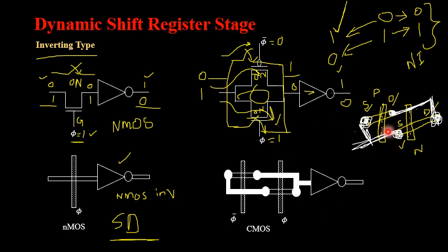Since I have told this particular transistor is a P MOSFET, so the polysilicon, that is control signal, is marked as phi complement. Similarly, I have marked this as phi complement. This polysilicon I have reserved for N MOSFET gate terminal or control signal. So obviously for N MOSFET it is assumed as phi here. So this will also be considered as phi. Then as usual, cascade it with an inverter. If you are supposed to draw this as an entire pure stick diagram, then replace this inverter with the stick diagram of a CMOS inverter.